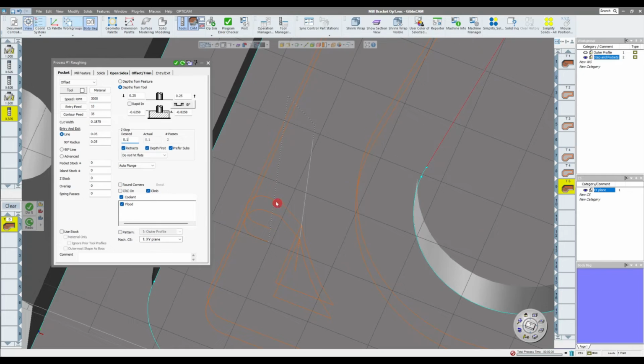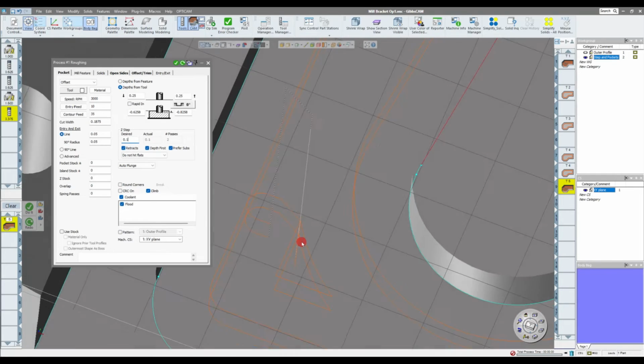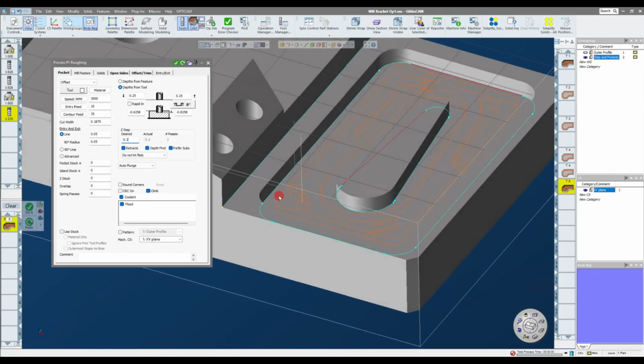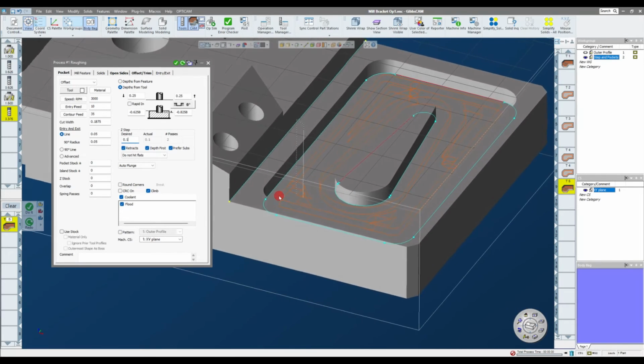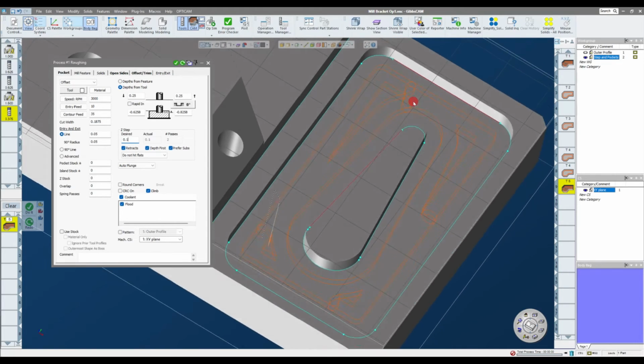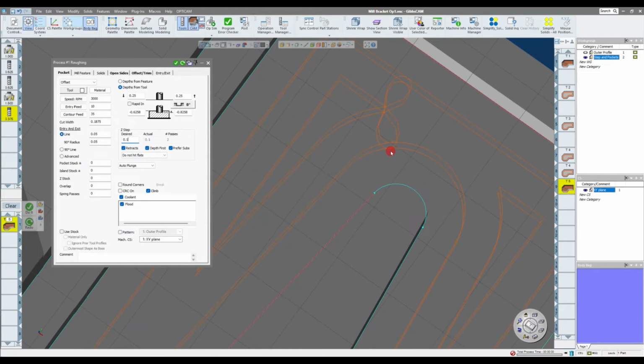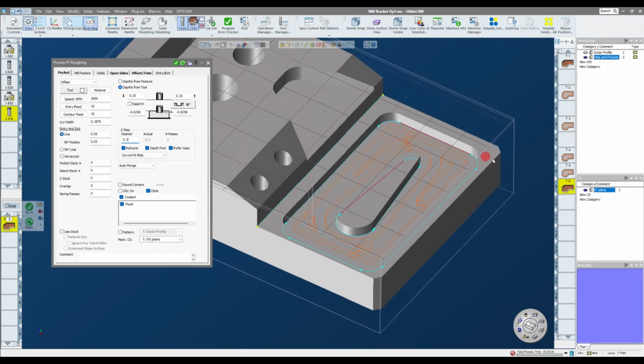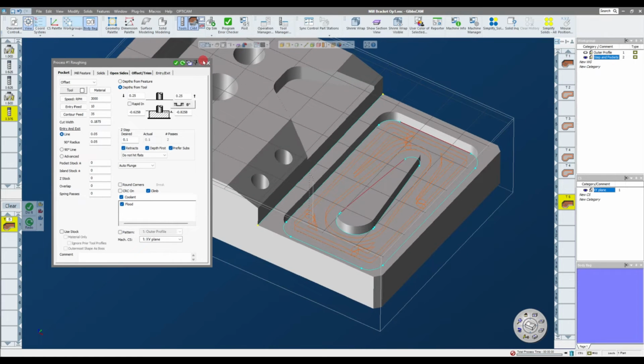And you can see the straight line radius lead in to each wall depth of cut to minimize a witness mark from tool deflection. And then you can even see it lead in and out of the island 2D toolpath. So there's my cut there.